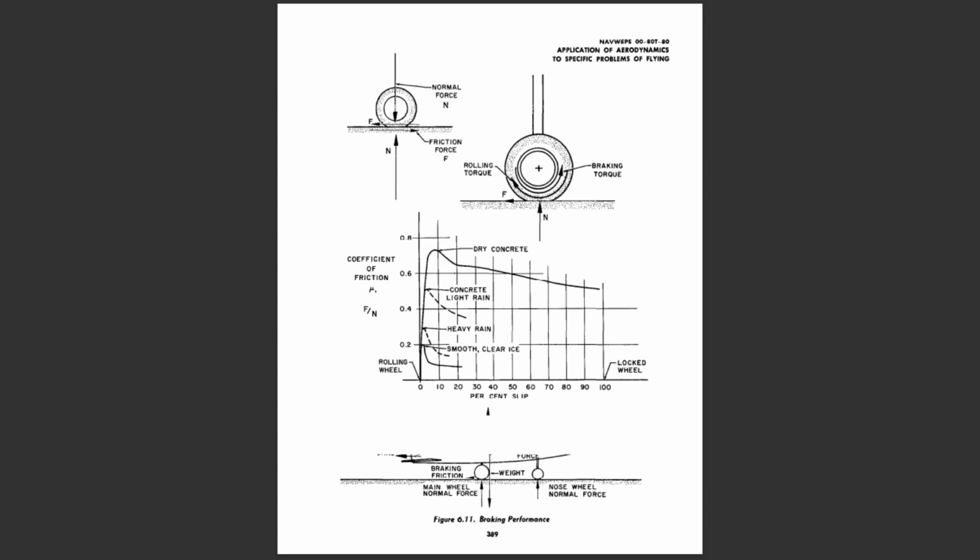When the runway has water or ice on the surface, the maximum value for the coefficient of friction is reduced greatly below the value obtained for the dry runway condition. When water is on the surface, the tread design becomes of greater importance to maintain contact between the rubber and the runway and prevent a film of water from lubricating the surfaces.